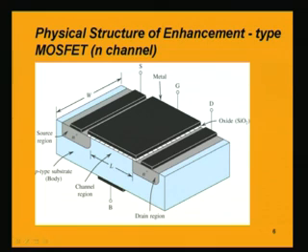So, these two N plus regions as shown in this block are two N type doping materials, and the P type and N type semiconductors both are grown on a single crystal silicon wafer. So, here actually the P substrate and the two N type semiconductors are grown on the silicon wafer, and as you see here, there is a silicon dioxide layer which is grown